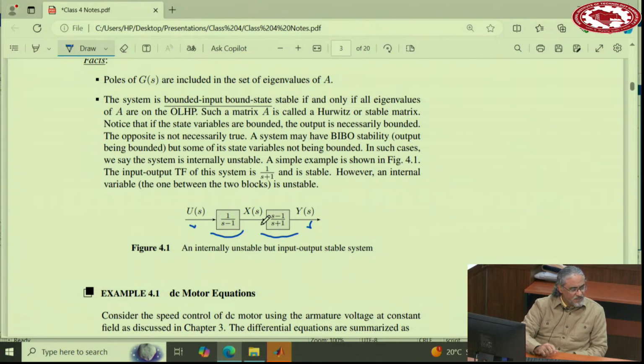So state space, and this is one of the advantages of a state space, because it really includes everything inside the system. Transfer function might occasionally ignore something. These cancellations happen. In physical systems, normally unstable cancellations do not happen, as far as I know. But there could be cancellations happen in a physical system which are not unstable, but which are close to instability.